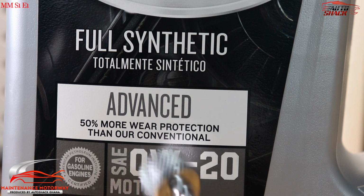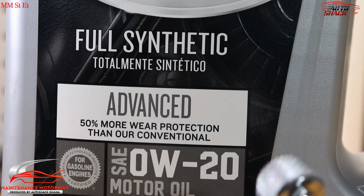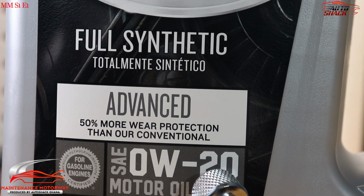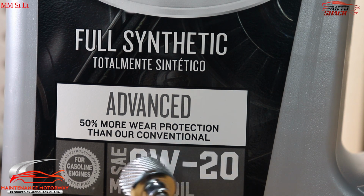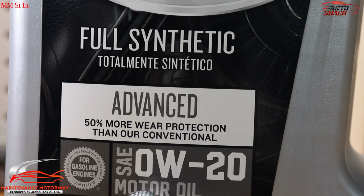The 0W20 and all that stuff is what you call the viscosities of the oil. Viscosities can be defined in several ways. In engineering terms, they can be defined in terms of flow rate, resistance of the fluid to shear, fluid layer friction, all that stuff. But for our purposes, we just define viscosity as fluid thickness. That's all we need to know at this point. So basically, the higher the viscosity, the thicker the fluid; the lower the viscosity, the thinner the fluid.